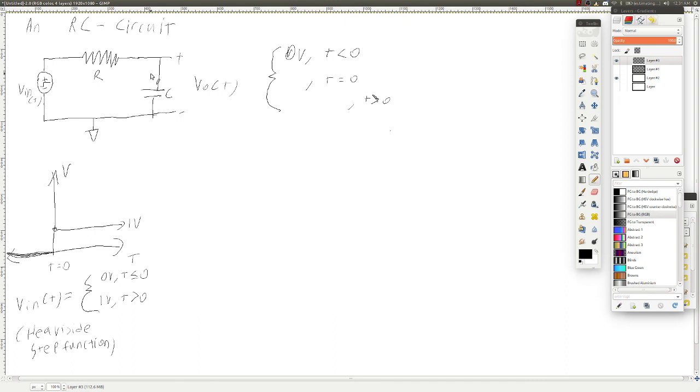The voltage across the capacitor is the derivative of the current. Nope, I got that backwards. The current into the capacitor is the derivative of the voltage. The voltage will start to pick up, but right now, the voltage is 0. Even though the most current there's ever going to be is at the time when this initially turns on, the capacitor has no charge on it. And no charge across a capacitor means no voltage. So at time t equals 0, the capacitor has 0 volts on it.